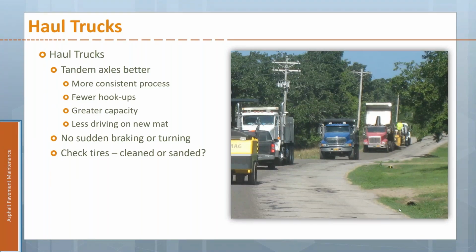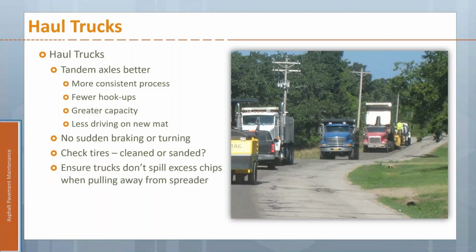But they should not be picking up your binder and carrying it off with them. And then make sure your trucks are not spilling extra chips as they pull away from the spreader. You don't want piles of extra material. Aside from the cost of it, it needs to be somewhere further down the road. It's also a mess that's got to be cleaned up.